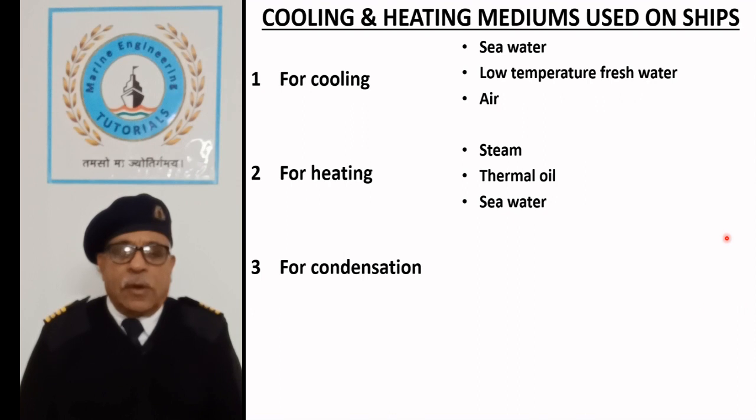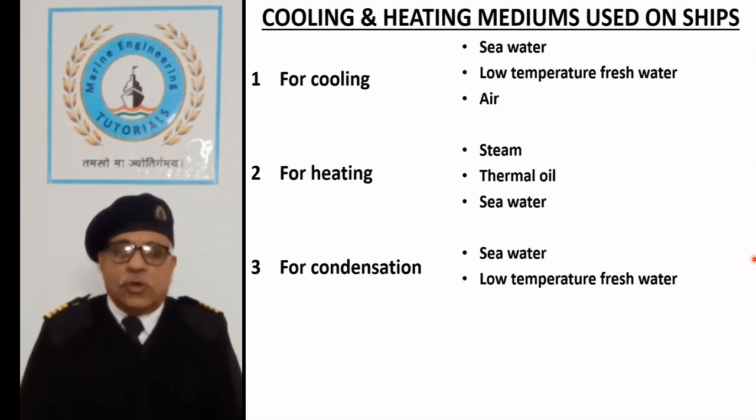For condensation. Seawater. Seawater is used for condensation of steam. Low temperature freshwater. Low temperature freshwater is nowadays used for condensation of vapors in large refrigeration and air conditioning systems. Air. Air is used for condensation of vapors in small refrigeration and air conditioning systems.